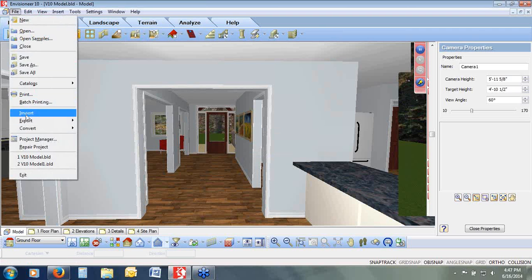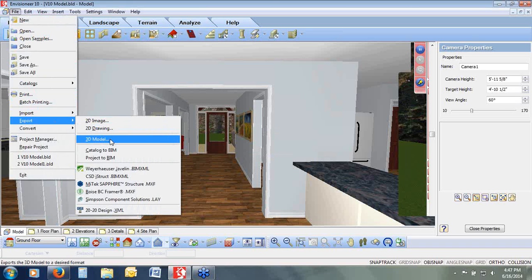If you export the software out as a 3D model to SketchUp, we've also done some enhancements there as well. We've consolidated the surfaces, so during the export process, similar surfaces are going to be consolidated, and that's going to give you a simpler and cleaner look when you go into SketchUp. We also will recognize the units. So when we export out into SketchUp format, they'll be scaled down into real-world units, so it'll be easier to use that conversion between the two products.